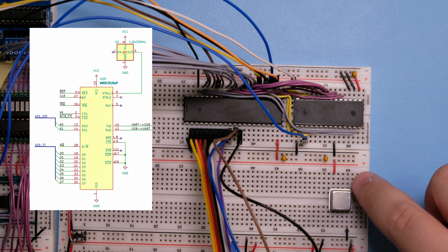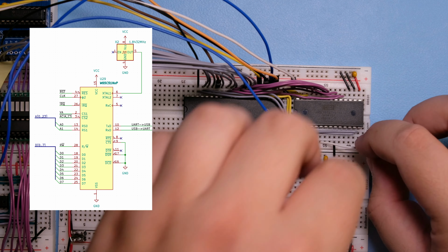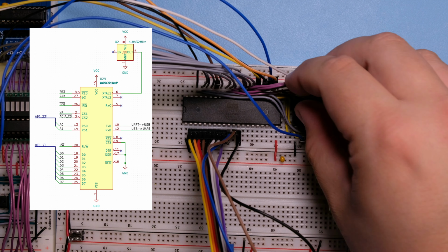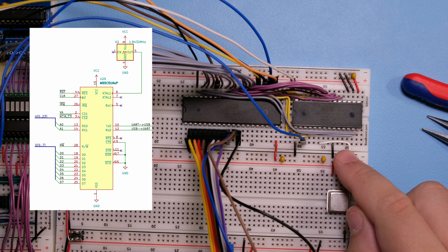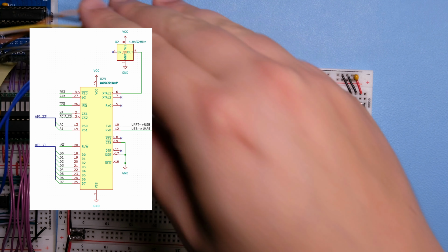And then the output is on the top right, and that has to go to pin 6 of the UART. And then we have our receive and transmit, which is pin 10 and 12. And for that, we need the USB to UART adapter.